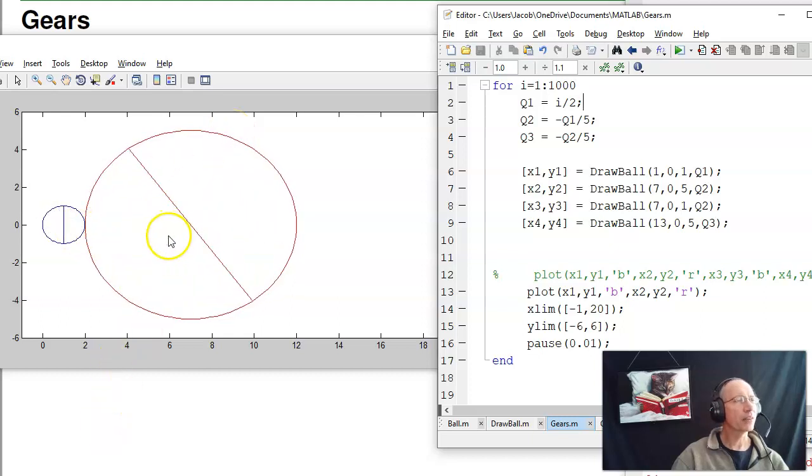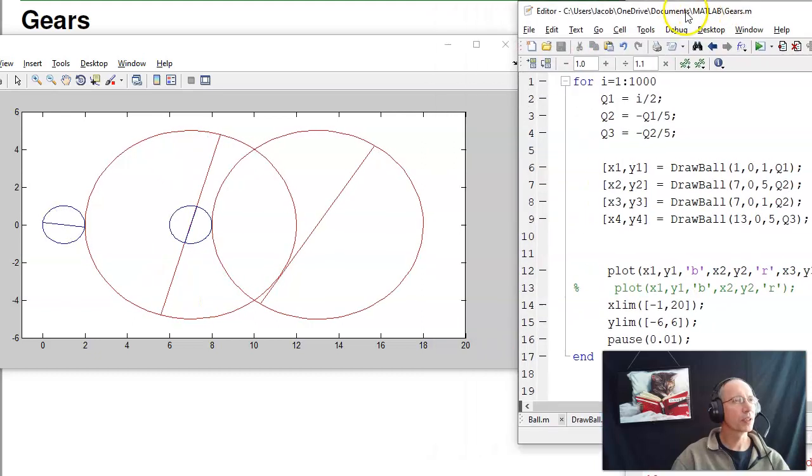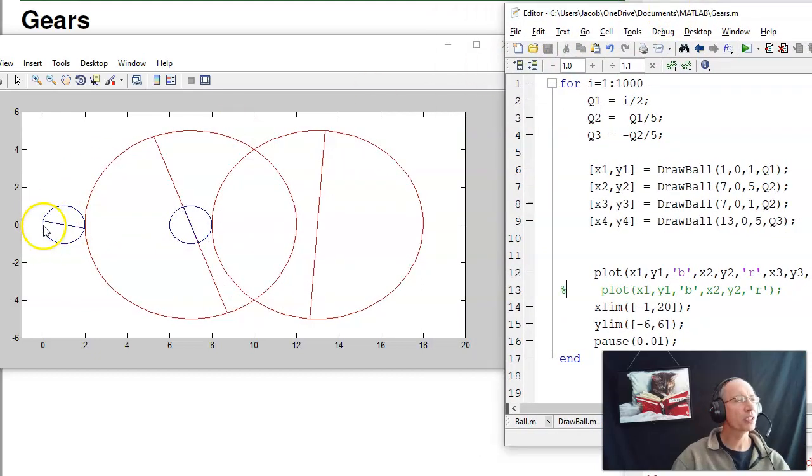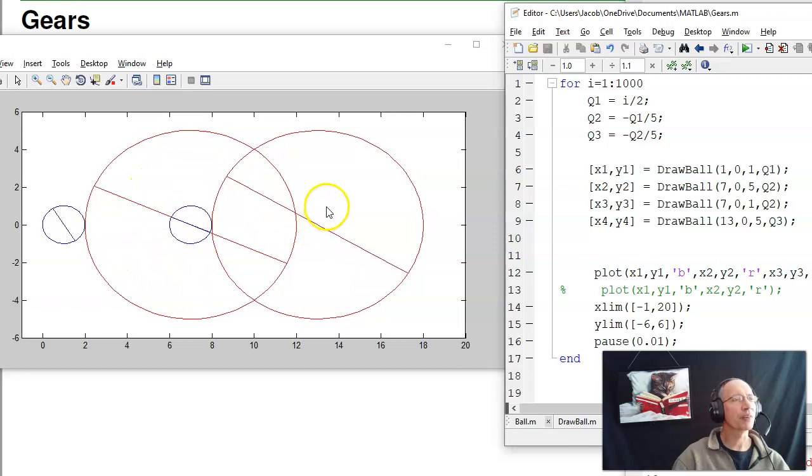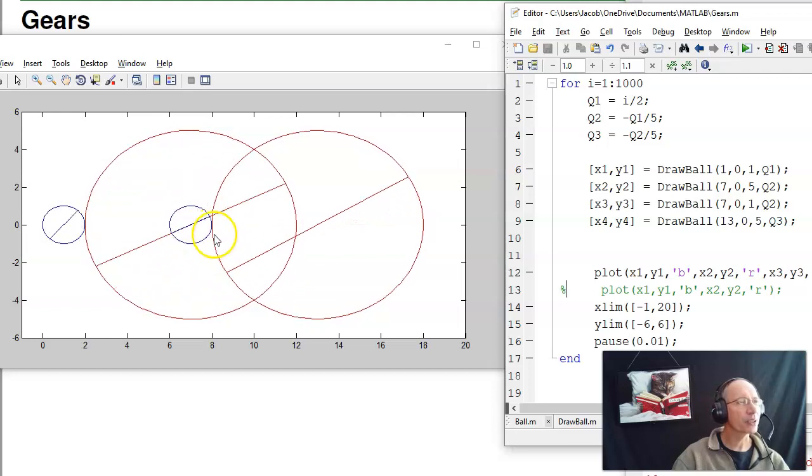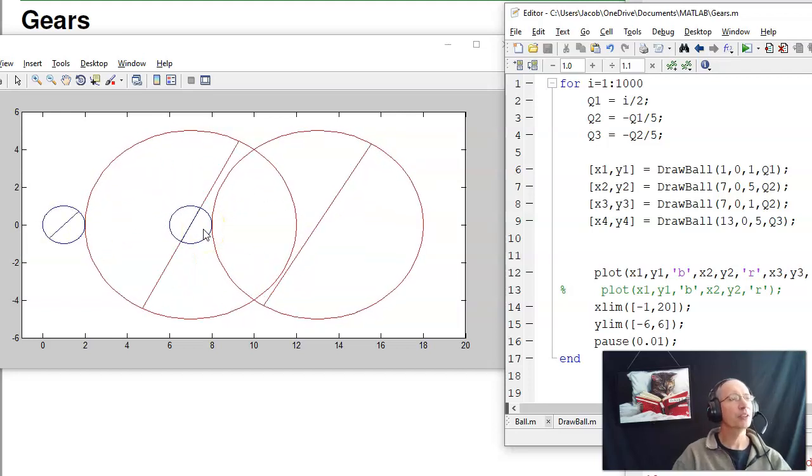And you can also have gears on top of each other. For example, if I have 3 gears, this small gear is turning the large gear, so this one moves slower. On top of the large gear is another small gear that turns another large gear. What happens is this gear spins counterclockwise, this one spins clockwise. Every time you go through a gear, the direction changes. And the speed slows down. As I have a small gear driving a large gear, the large gear slows down. Small gear driving a large gear, this one slows down as well. And right there you can notice, right when that goes through this point, the 2 speeds match. So gears are a way to change speed.